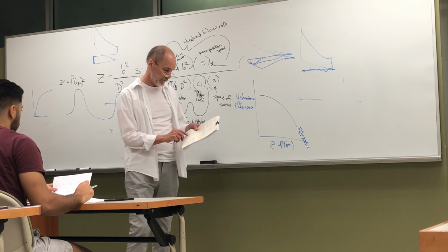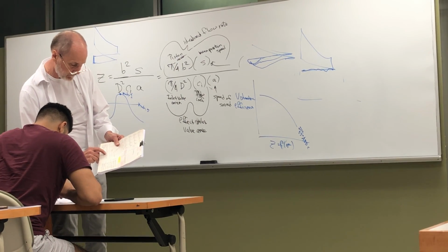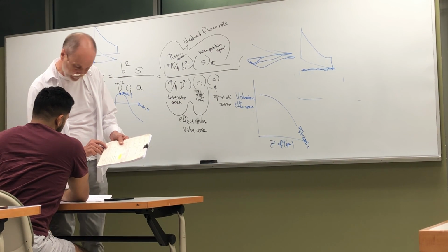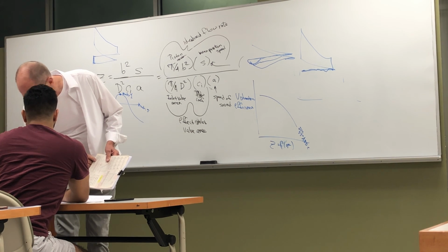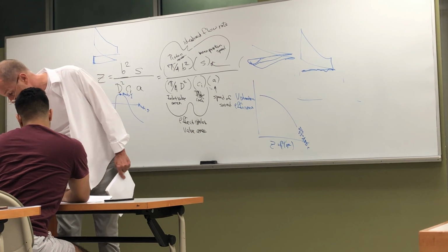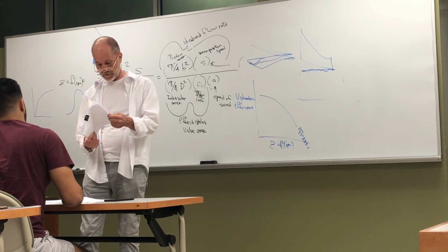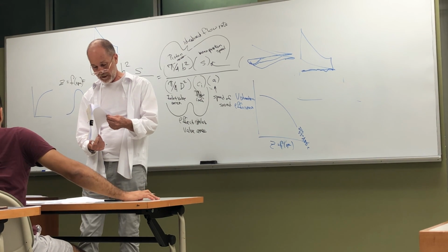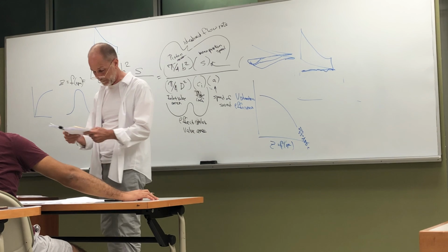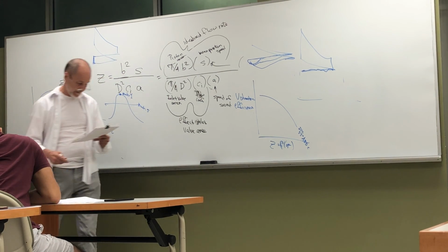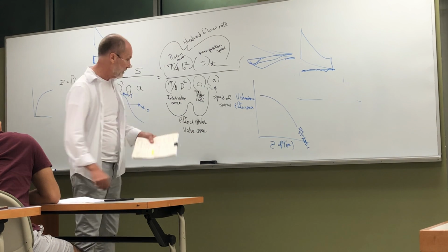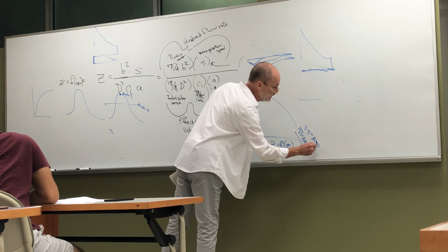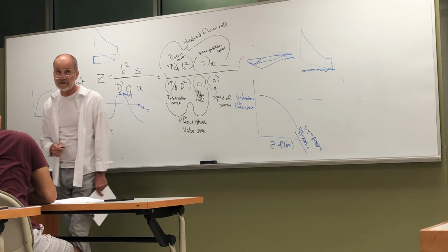Why does the Mach index number go over 1? This is 55 degrees after bottom dead center, and it stays constant. What is that? I don't know. I must have Xeroxed the one that, I apologize. At the bottom it's supposed to say 55 degrees after bottom dead center, as it does on mine, but not on the Xerox ones. So this would be 55 degrees after bottom dead center, not before. That's when the intake valve closes.